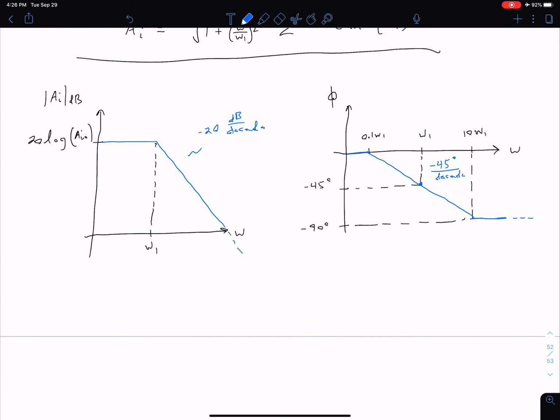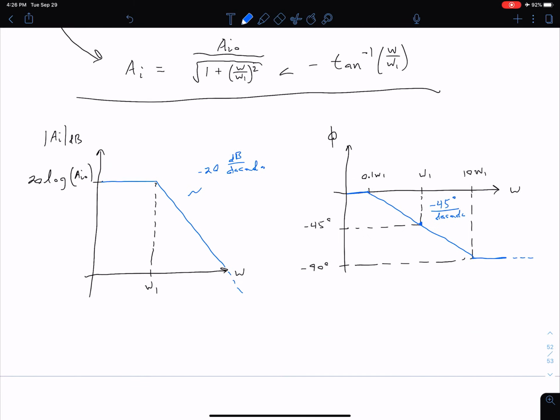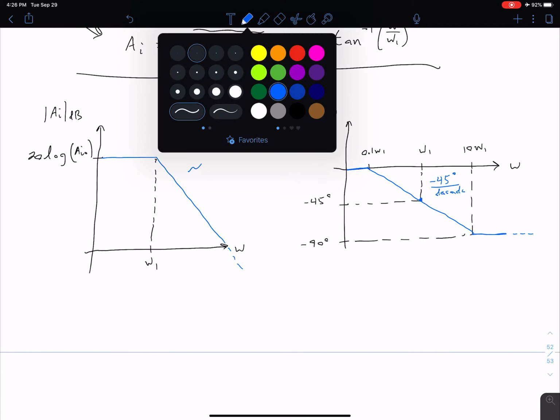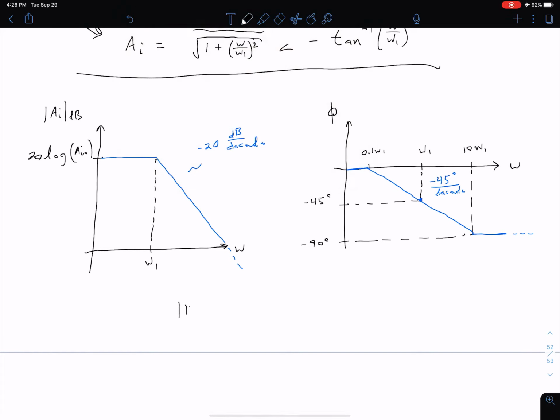We're not going to spend too much time talking about this because we want to move on to look at our 2-pole and ultimately our 3-pole amplifier. But to get an idea of where we're going, we're looking at the magnitude of our loop gain and the phase of our loop gain, and we said that at a certain phase, negative 180 degrees, depending on what the magnitude of our loop gain is, our circuit is either going to be stable or unstable.